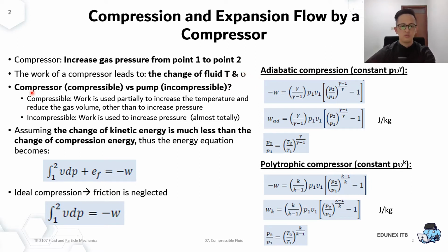Why? Because a compressor is used to compress a gas, which is a compressible fluid, and that's different compared to a pump, where it compresses liquid, the incompressible fluid. So which one is more effective or efficient? Actually, it is much easier to compress liquid using a pump, and it is more energy efficient.